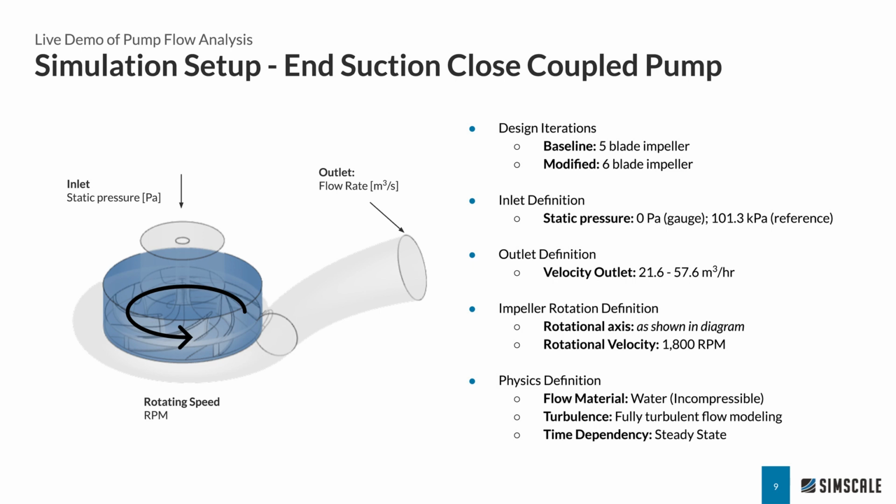And just to define the physics of what we're simulating, we're working with water, fresh water, so incompressible flow, modeling full turbulence, and working on a steady state time dependency for this setup. Let me go ahead and quickly shift over to the SimScale platform to give an idea of what the workflow to set up these simulations looks like.